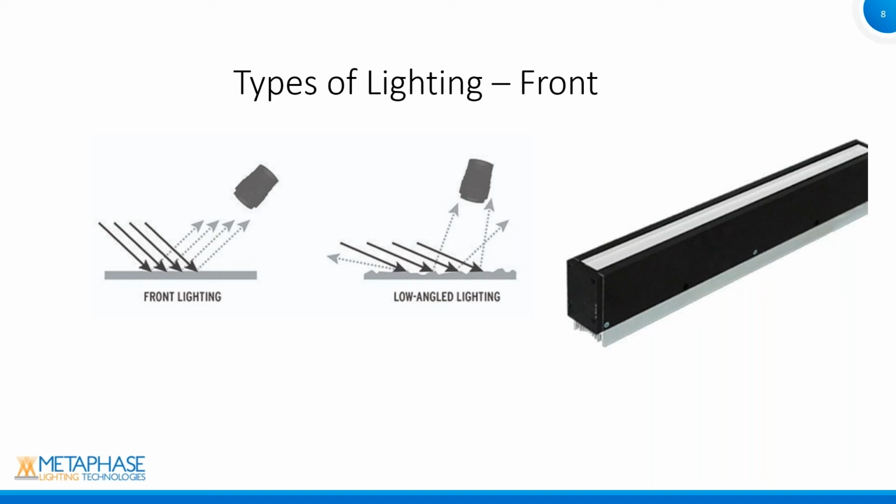In this case, some very generic examples: with front lighting, with line lights, you'll typically have an angle that's the camera with the beam pointing down. So that way, as the material is traveling through, you get basically every single part of that given web. When it comes time to do more dark field applications, we can use the same type of light, but just at a much lower angle. This is really valuable for helping us to pull out textured surfaces or structured features like you would see in a woven or a fabric material.